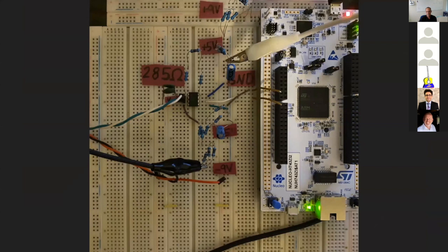And this is our integration circuit that scales our sensor's output to a voltage range that the STM's ADC can take in and convert to digital values before sending this data to the bunker computer. The white and green cables on the left are the data output pins for our sensor. They are going into the instrumentation amplifier, which is the black chip in the middle.